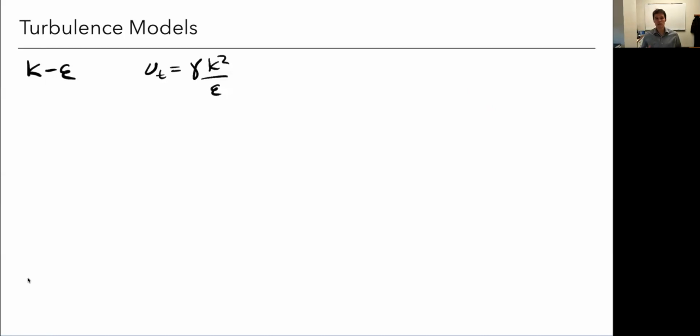So all of these turbulence models have these tunable constants, and the K epsilon one I think has 5 constants. So again, sort of kick the can down the road. I built a model, but now I don't know what gamma is, and there's 4 other constants I don't know. So these get tuned based on experimental data. So if you choose the K epsilon model, there's going to be some defaults. But in some cases, you may have to tune those constants. Most commonly, you might just use the defaults, but certainly in some cases, these are things that can be adjusted.